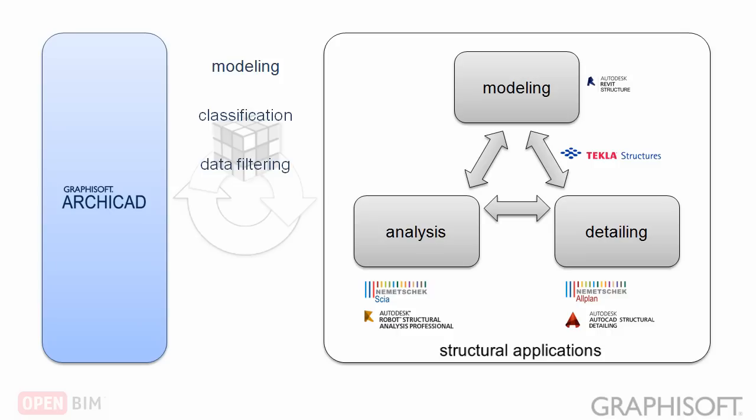For example, accessories such as a fence, bench, or parked car, these are not part of the model's load-bearing structure. The structural engineer does not need a detailed window structure when the window's bounding box will suffice. For import, if I receive a large database, I should filter for the information that I need. Export the models. Import the model and place it as a reference model into each receiving application. Change management. That is, managing the version changes in each discipline's model.